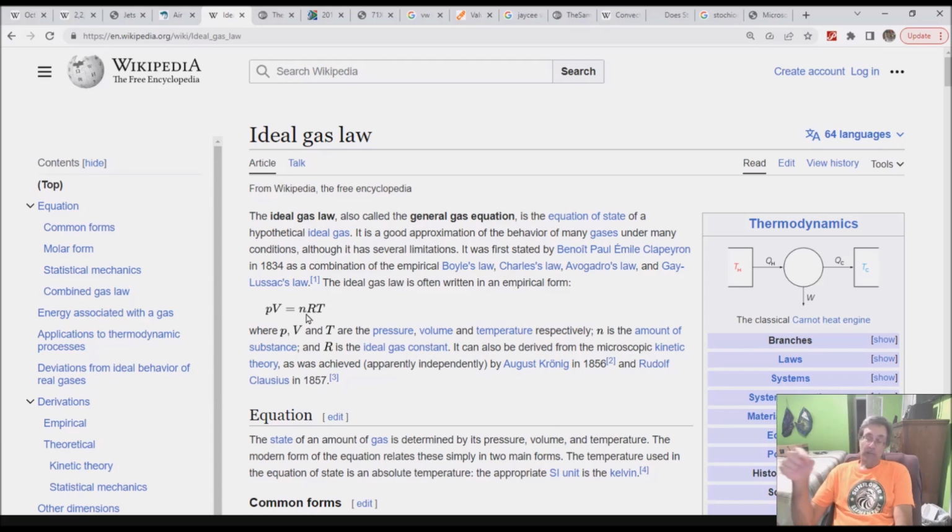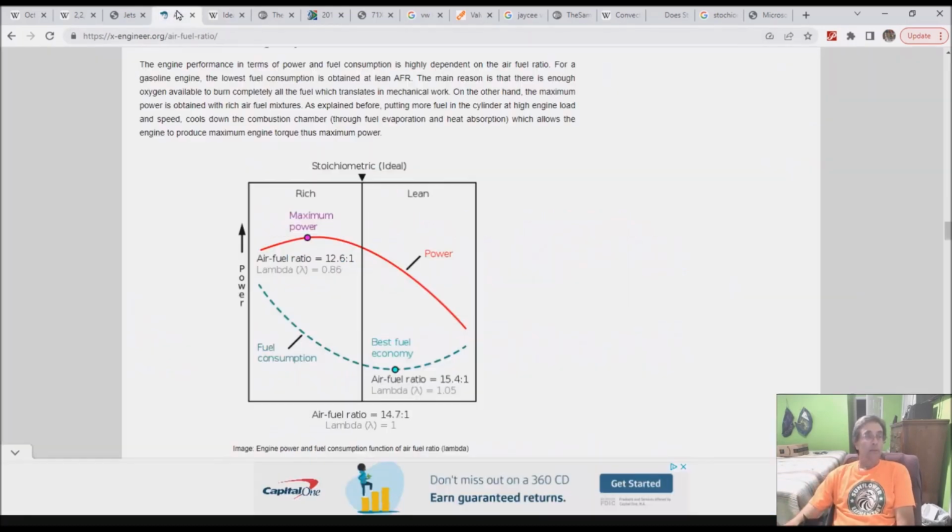So if you take the gas and you burn it inefficiently, let's go back to the graph. If you take the gasoline and you burn it inefficiently, notice that this is an efficiency curve. We're efficient here, we're inefficient over here. So you're burning it inefficiently. But the liquid gas is allowing you to put additional air and additional fuel into the system. So even if it's inefficient, you can overpack the system with fuel and air in order to make up for the lack of efficiency. This allows you to make more power.